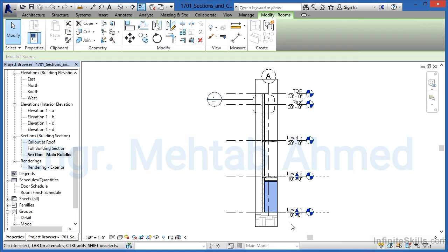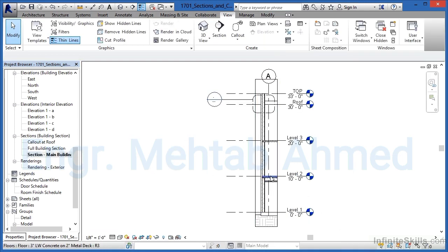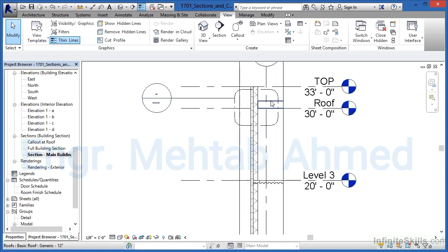And here we can see where we have the floor down below. We can begin to see the floors coming up. Right here is a roof. And we can see this is the outer wall that it's cutting through. This entity here with a circle with a few dashes in this line, this is what's called a callout. It's also used to be able to create enlarged details of spaces.